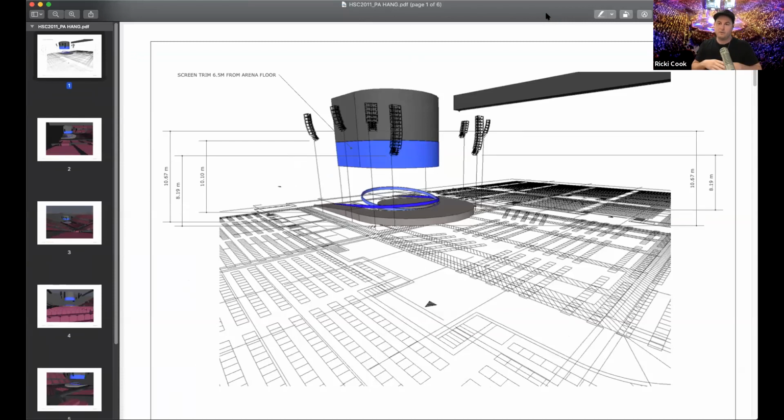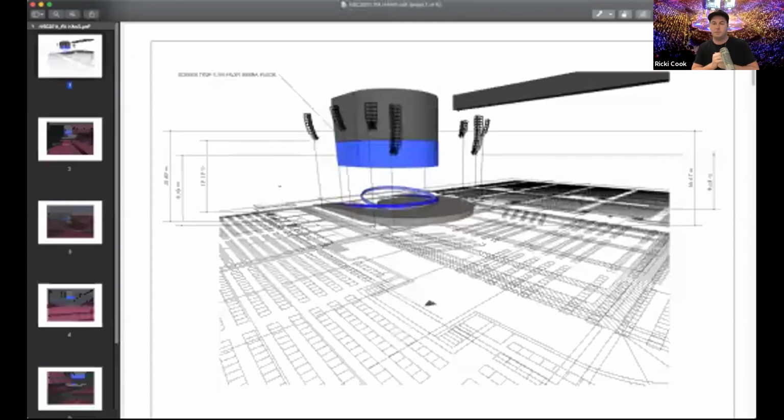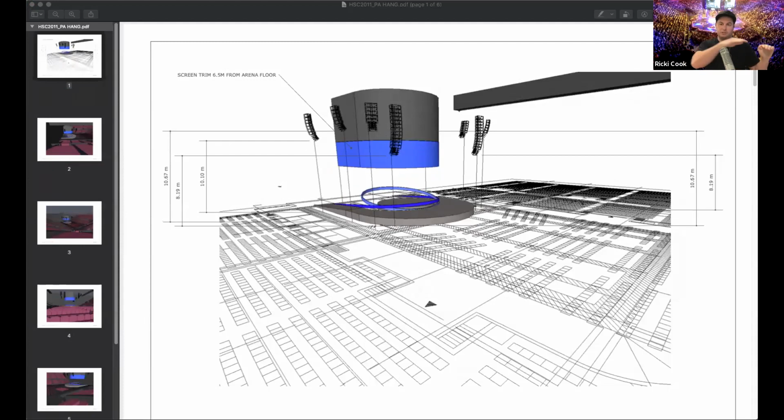Now, to cover that overlap, because when you put a PA in, and Josie can talk about this more with the 6 dB down points, you need to be able to create a very smooth transition between the arrays. But because we went from what would be a left, a right, to a left and a right, we decided to switch those around and add another array in.